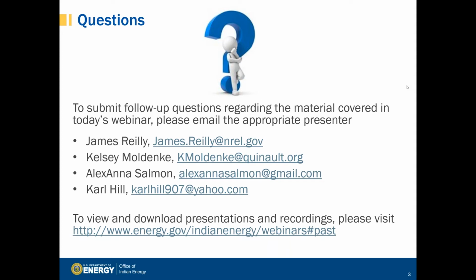But yeah, there are investigations of supercapacitors coupled with energy storage and things like that. There's also some inherent storage within the inverters themselves. A lot of inverters have capacitors and things like that built into them to try to help smooth it. But yeah, energy storage and also just managing the PV through meaningful, purposeful curtailment are two of the primary ways that are done to try to manage variability.